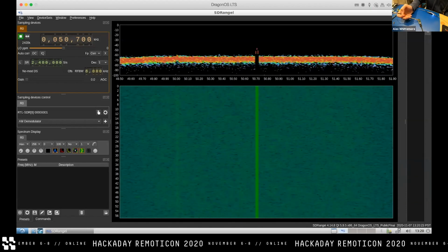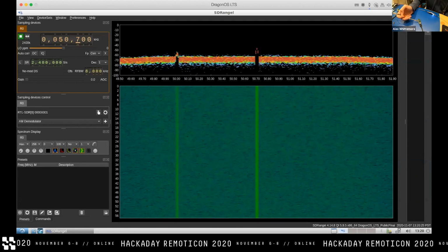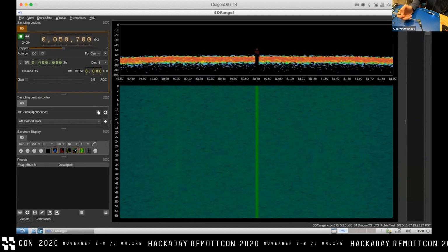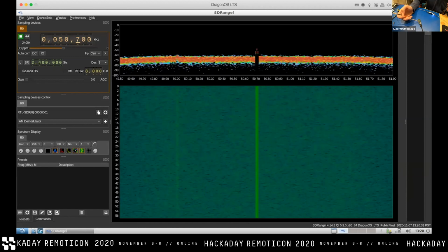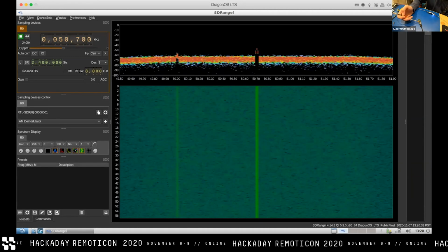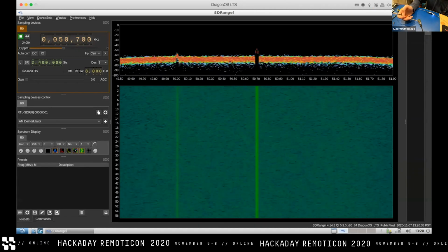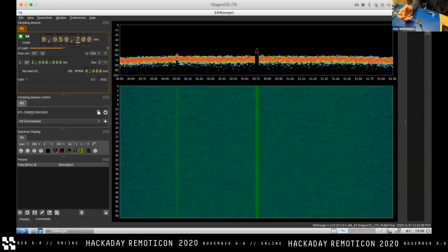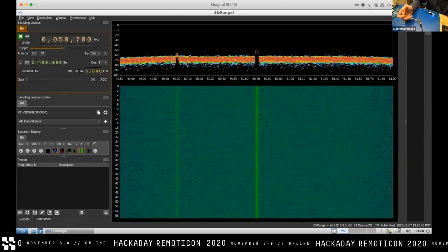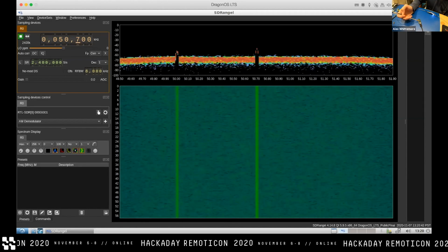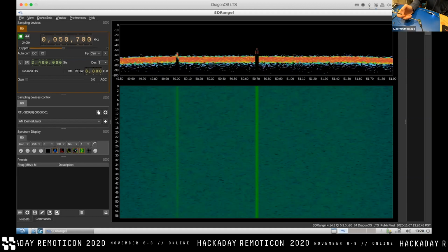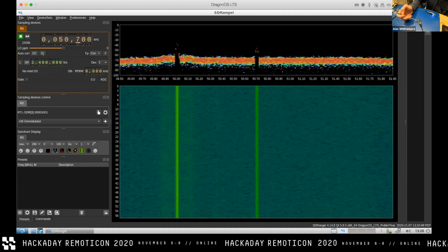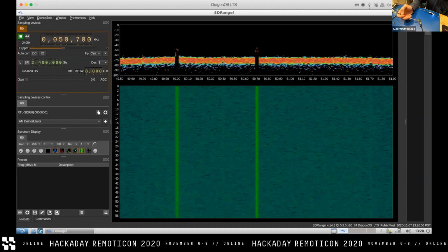Turns out we're emanating the signal in a very specific spatial region. And this is why you start with the bigger probes, because it'll pick up much more and give you an area to narrow in on. If we wave this probe over here, though, we start to see that signal perk up, and I'm not quite sure if we wave it directly over the FPGA. It seems to be up there. That's definitely interesting. Ooh, something seems to be going on over there.